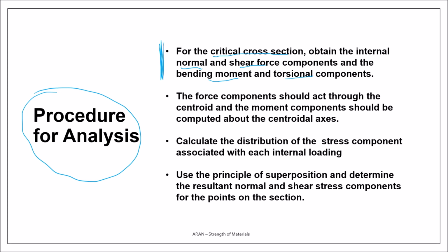But all these forces should act through the centroid. Otherwise there will be some bending moments created and our formulas will not be valid. All the forces should act at the centroid, and the moments should also be computed about the centroidal axis.